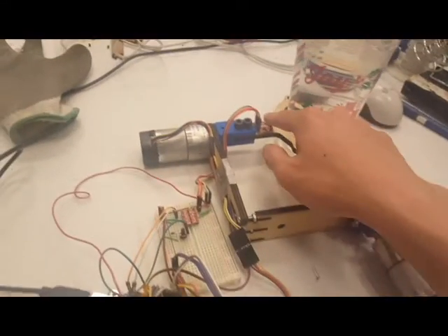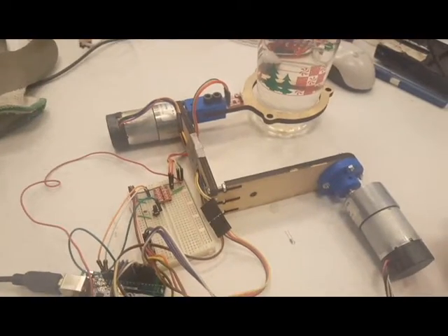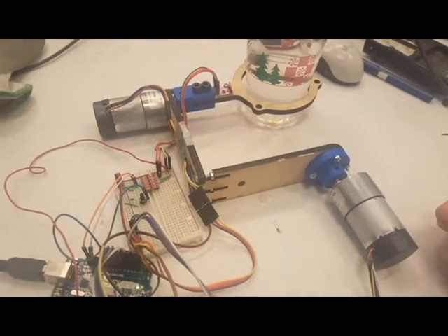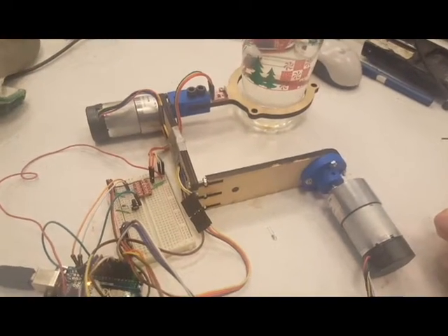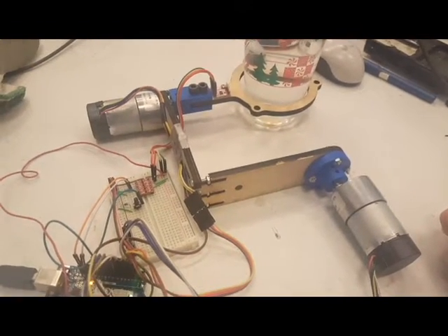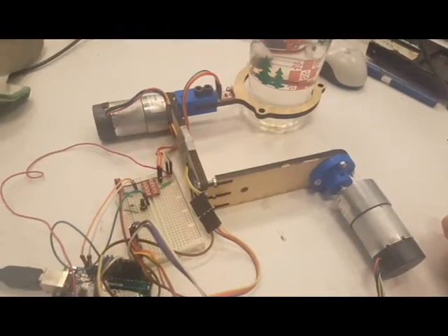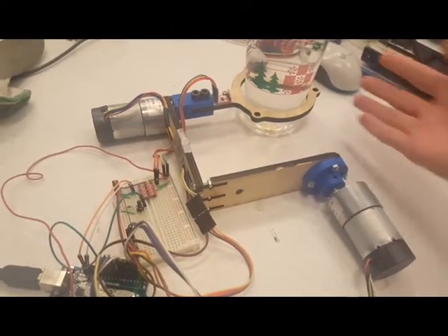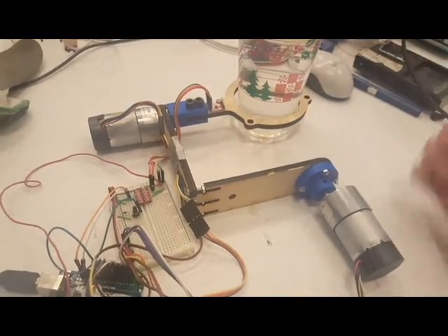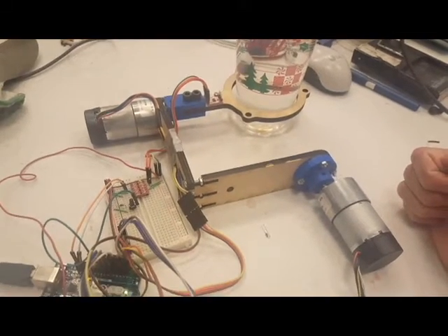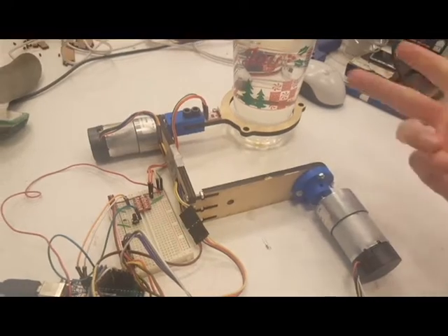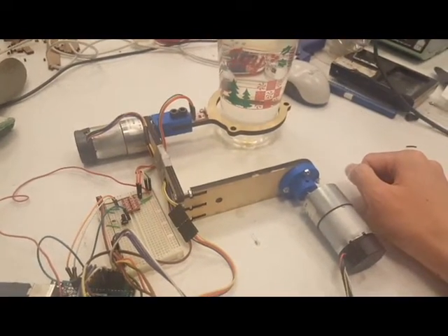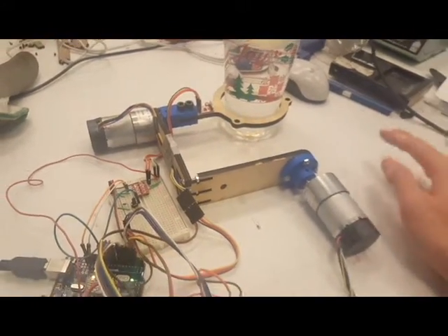We have the IMU, which is the main sensor for sensing our orientation. It is actually the 9 degrees of freedom IMU, which means that it has a 3-axis linear accelerometer, a 3-axis angular velocity gyroscope, and a 3-axis magnetometer. Because we're trying to cancel out the effects of the gravitational vector, the magnetometer is not as useful as the other two, since it only dictates your yaw direction as opposed to the pitch or roll.